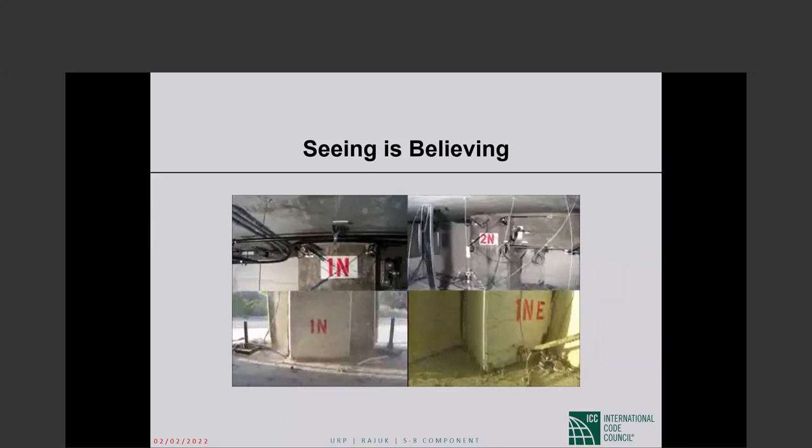There is no dual system in wind design. This is all seismic. If you want to do a dual system in wind design, you will just do the interactive analysis. No 25%. It doesn't make any sense. The whole basis of the 25% frame is that if something happens to the shear walls, the frames will still be standing up.